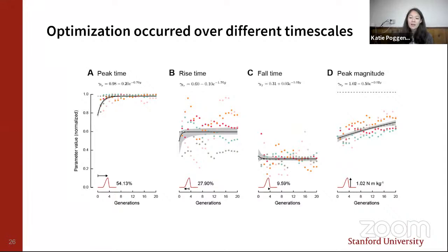I worry that if we put too high of torque into the system initially, people might adapt to that robust kind of gait. So it may actually take longer to unlearn that robust behavior and learn to take advantage of it. So the way that our optimization worked is we had 2-minute periods where we changed the controller every 2 minutes. We have not looked into more of those slowly evolving kind of trajectories.